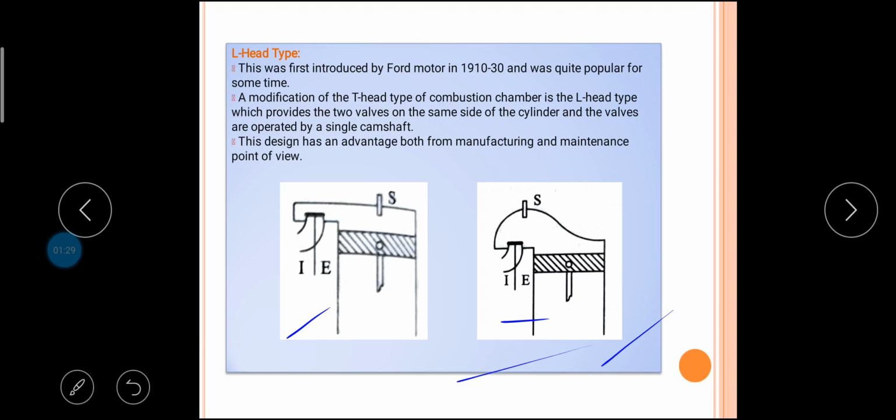This design reduces the knocking tendency by shortening the effective flame travel length, by bringing that portion of the head which lay over the further side of the piston into as close a contact as possible with the piston crown, forming a quench space. The thin layer of gas loses its heat rapidly because of the large enclosing surface, therefore avoiding knocking. By placing the spark plug in the center of the effective combustion space, slightly towards the hot exhaust valve, the flame travel length is reduced.